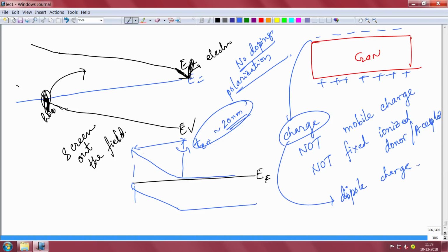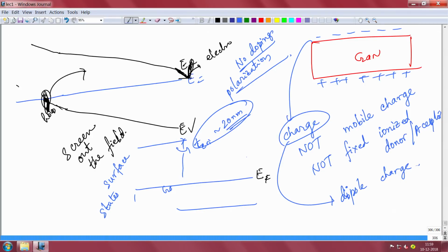But again this assumes that on the surface there are no impurities or states, but in gallium nitride technology there are typically always surface states. These surface states are essentially traps and donor-acceptor kind of levels on the surface, which have different kinds of effects. One effect is that the surface states or traps will pin the Fermi level, which means they fix the Fermi level at one point and not allow it to move through the entire band gap. So if this is a Fermi level, it will get pinned at some value here. Instead of the whole band gap dropping, you will drop only some part of the band gap, because these traps are pinning the Fermi level. The Fermi level is not allowed to move.